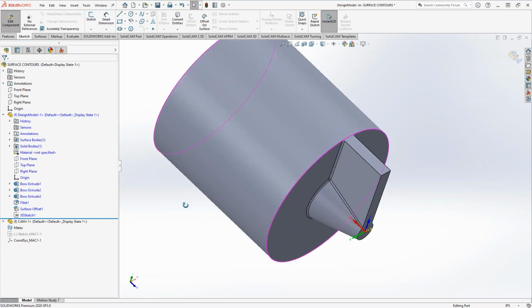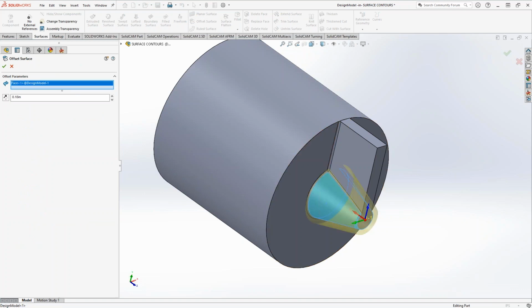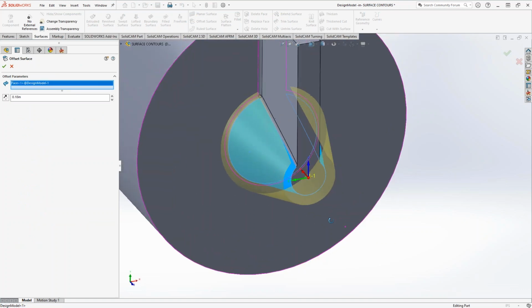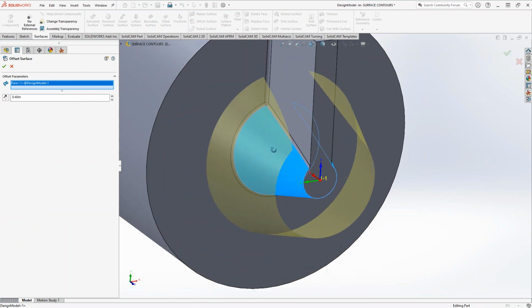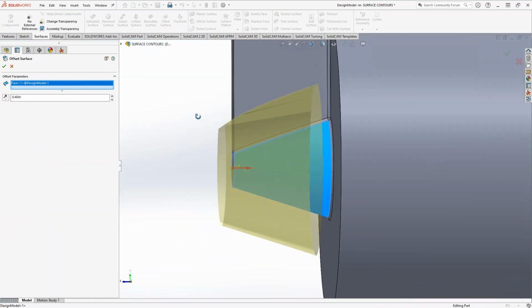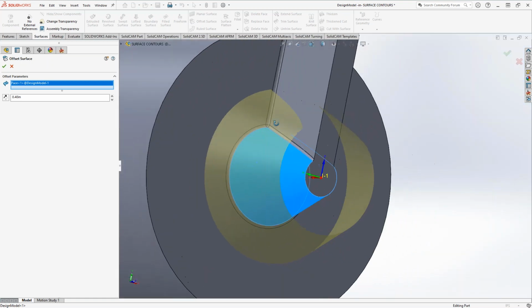and hide that. Okay. So that functionality, again, is in the Surfaces tab. And if you go to, see if I can remember it again now. Oh, I love doing this live and then forgetting where I went. Okay, I think it's Offset Surface. There it is. Click on that surface, and now you can see that it gives me an offset from the surface that I selected, but in the surface normal direction. So it's essentially offsetting on all edges. I'm giving that kind of 3-dimensional 5-axis kind of thing there.